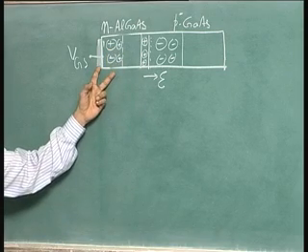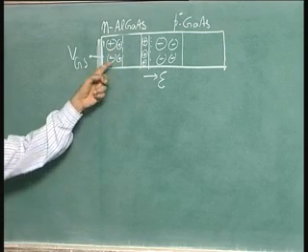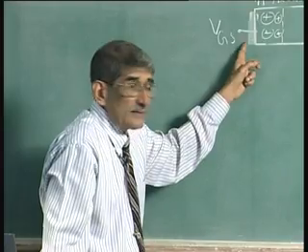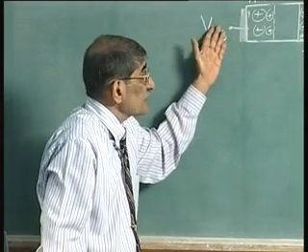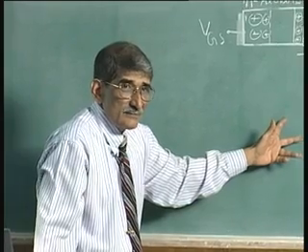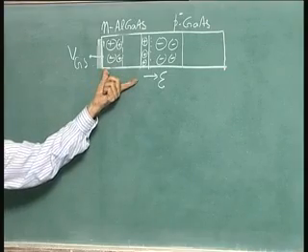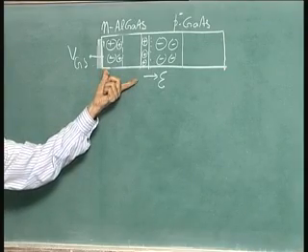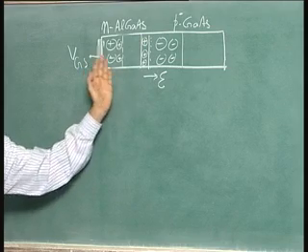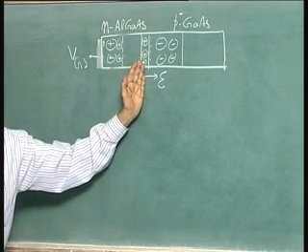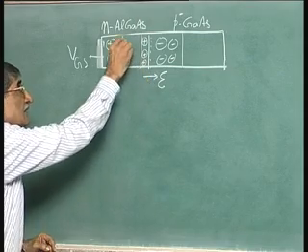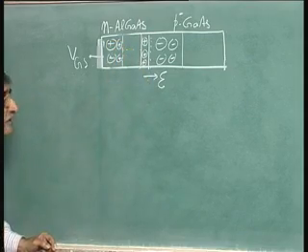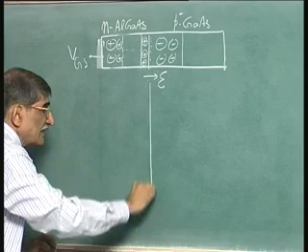Built-in potential, okay, plus here, minus here, there will be an electric field from this side to this side. As I keep on increasing the gate-to-source voltage, this depletion layer keeps on moving. At a particular voltage, the entire layer will be depleted. Okay. So, this keeps on moving. So, let us just plot the electric field.